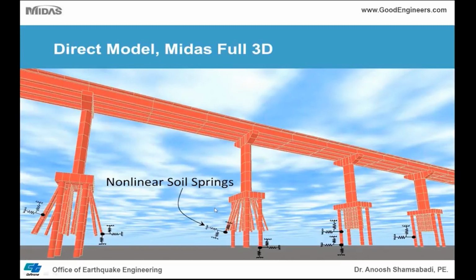So here is another rendering of the closer shot of the Midas. You can see these are nonlinear springs attached at the tip and along the pile. Just because there is not enough space to show all the springs, I just put some springs as a schematic representation of the nonlinear springs. But all these nodes, you can see all these lines, they all have 3 component springs attached to them in the longitudinal direction, in both longitudinal and in the transverse direction, as well as the vertical direction, which is called PY, and this called TZ, and at the tip we call them QZ curves. So they are all incorporated in the model, including massive pile cap and the superstructure.